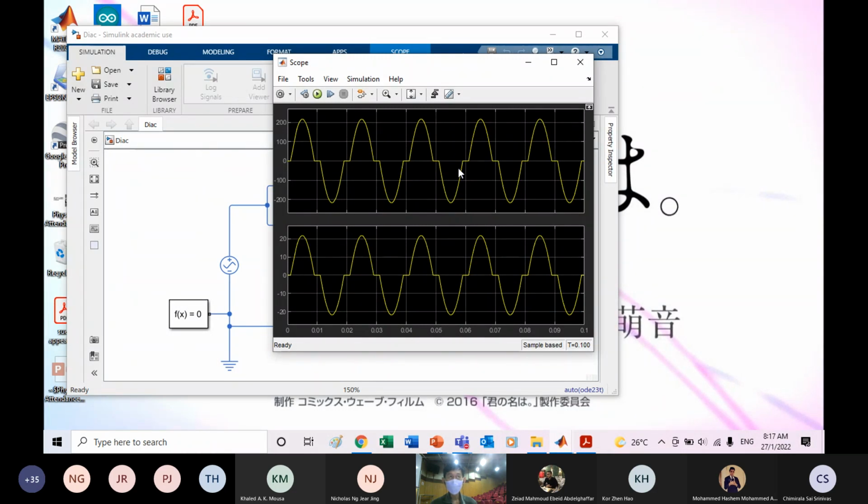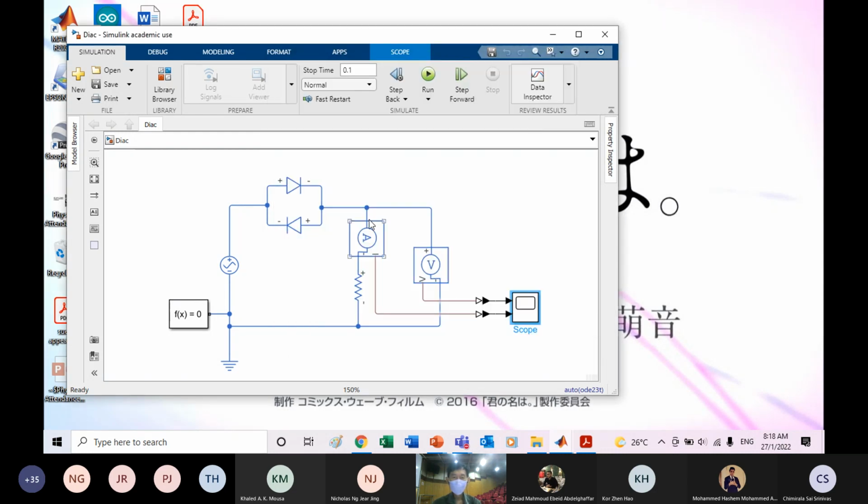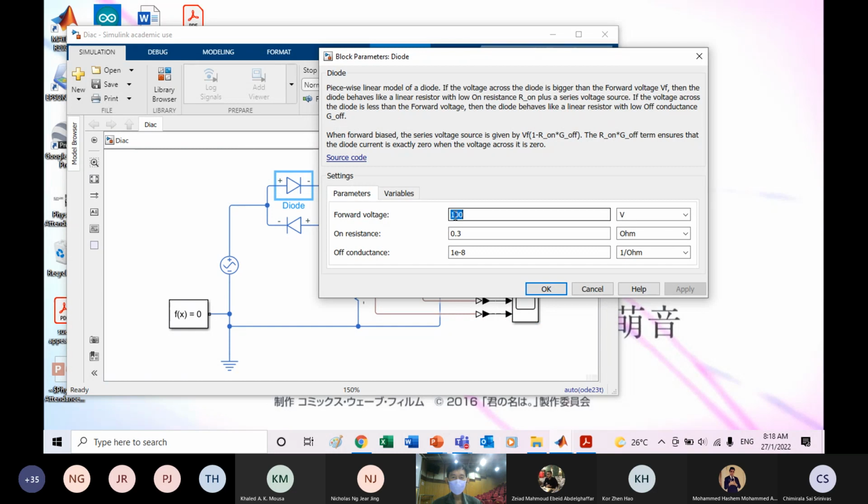Now, previously we chopped off by the side, or angle, or you can translate it to the time lah. You chop off by the side, but this one you chop off vertically, not horizontally. So in this case, how much you want it to chop off depends on how high is your, what we call this, your breakover voltage. So if I change it to a little bit higher,